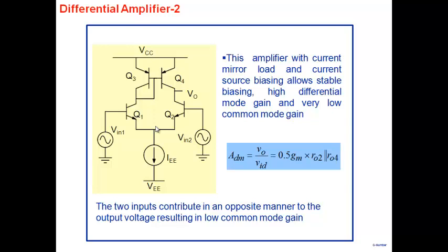You can't make any of those approximations, and only then you'll get the right estimate for what the actual value of gain is. So what we can see here through the circuit is that common mode gain is going to be very low. But how low, as I said, well, you have to do an exact analysis to get that. And otherwise, of course, you have the simulation to give you the right answer here.